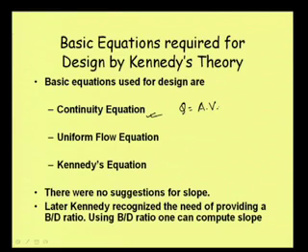And then we should use the uniform flow equation, because we always design this canal for uniform flow condition. There are several uniform flow equations, as we know: Manning's equation, Chezy's equation, Kutter's equation, Bazin's equation, different equations are there. While designing this canal, people generally prefer Kutter's equation. They use Kutter's equation. But of course, we can try with Manning's equation also.